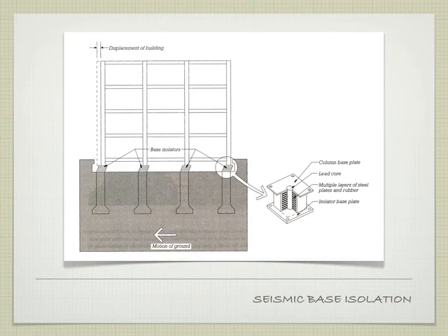And what it allows you to do is, when the building is sitting stationary, it's perfectly fine. But then these isolators, if an earthquake were to happen, would allow the building to move up to a foot in either direction when the earthquake hit. I've heard of skyscrapers having these and being able to move up to 3 feet. So depending on the scale of the building, you're going to move more or less.